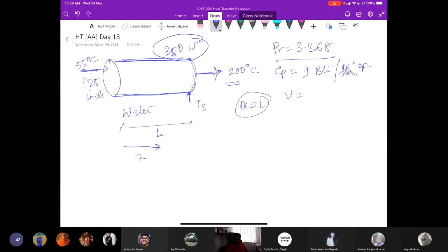I give you the value of nu as 0.57 times 10 to the power minus 5, here in feet square per second. Thermal conductivity I give you as 0.374 BTU per hour feet degree Fahrenheit instead of watt per meter Kelvin. I give you everything in this format so that calculation of these parameters becomes easier.